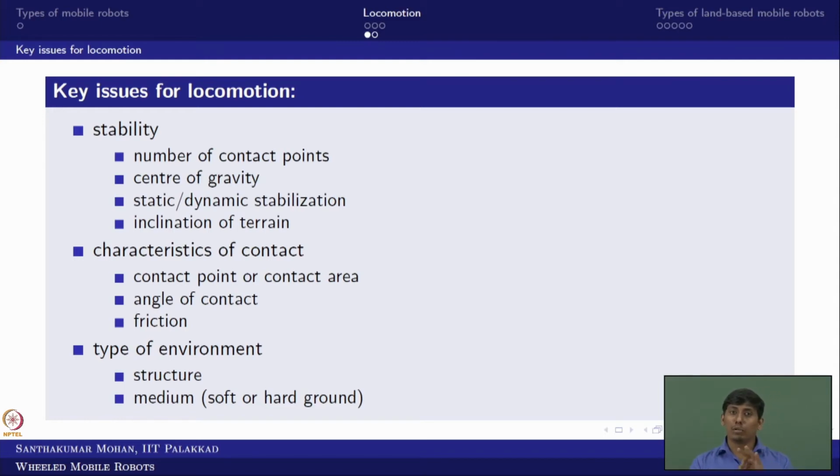Now this friction is not the only thing. It is also ensured based on the contact region, whether it is a point contact, a line contact, or contact over an area. For that you can take an example, a normal car. The car tire can be a radial tire or a non-radial tire, right? The radial tire is more generally used these days. Why? The radial tire makes more contact area. It flattens and sits on the ground. So that is what we are understanding.